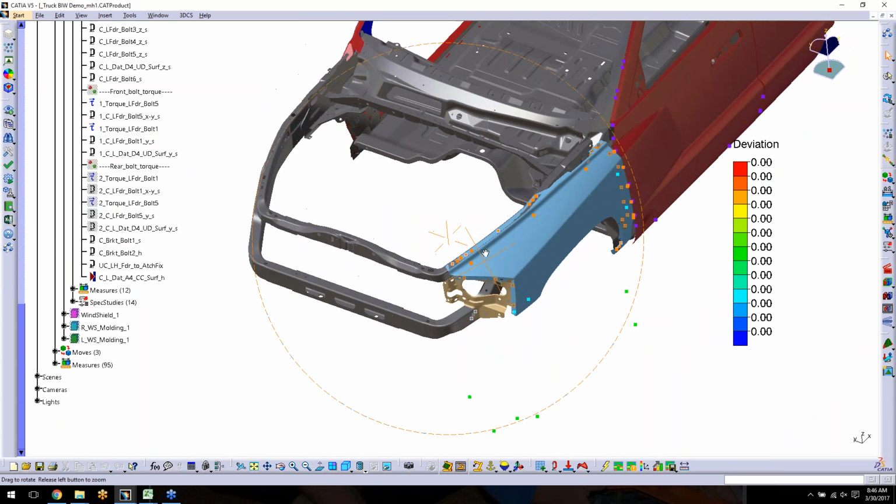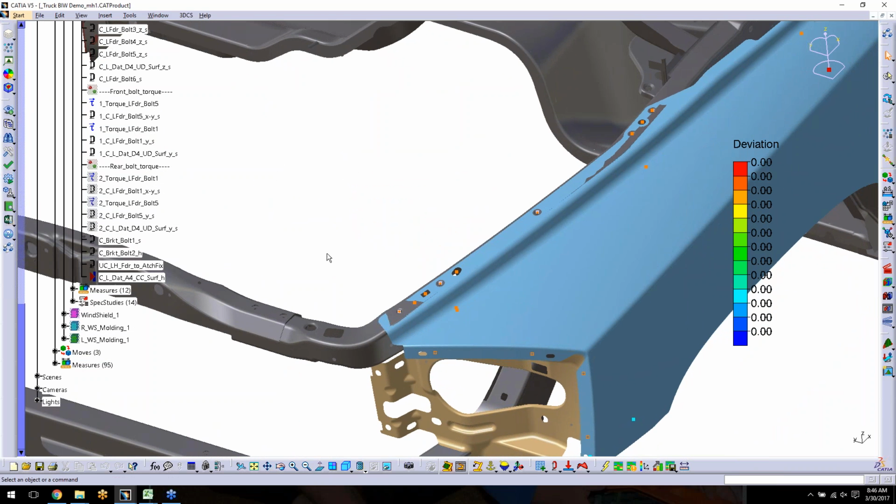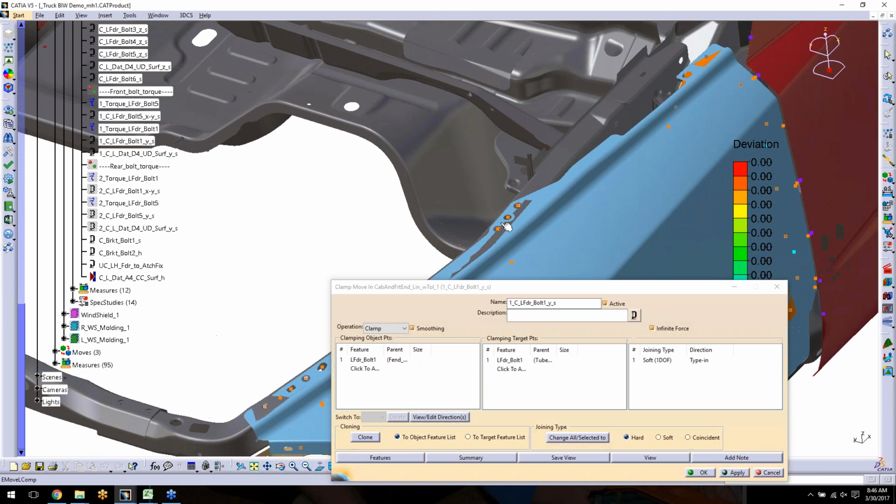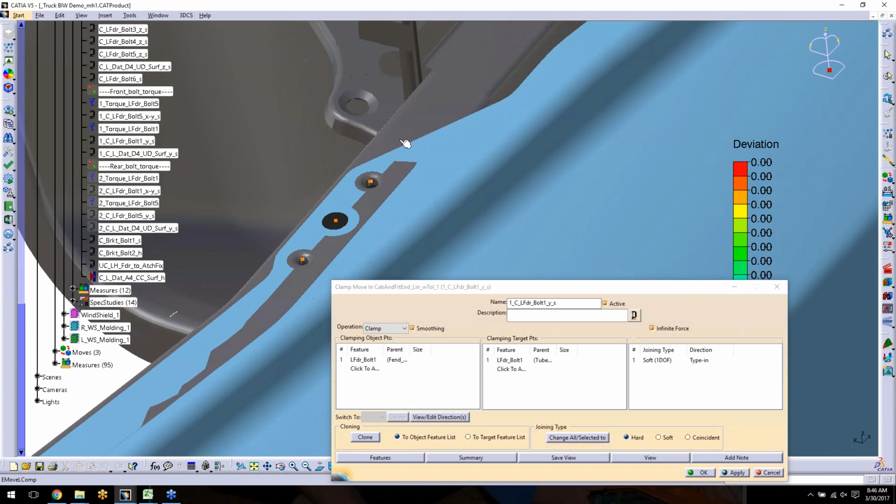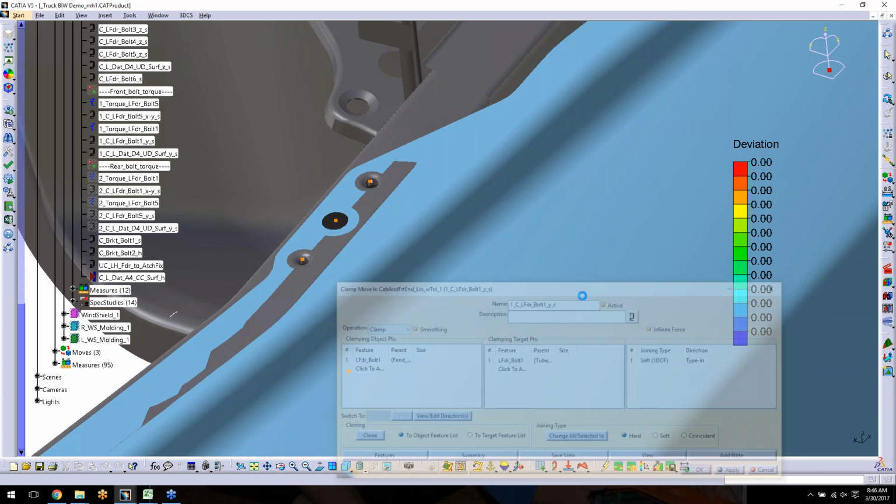And you set up these directions. So once I brought that point back to its location, the next move would be I'm torquing this bolt now. Same idea as the first torque. And then I am going to soft clamp it, but in only one direction. So I'm not going to force this point in this direction. I'm just going to force it back to overlap with the hole in just Y direction.